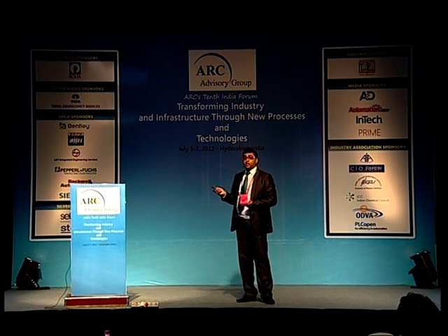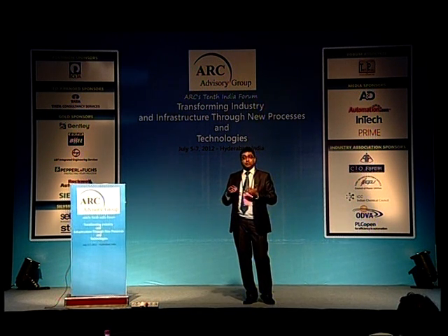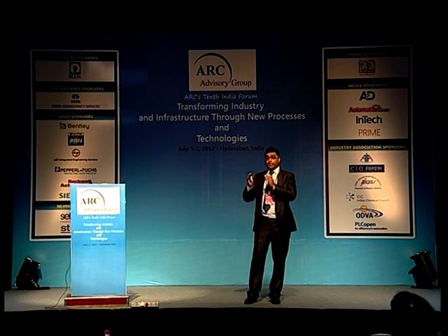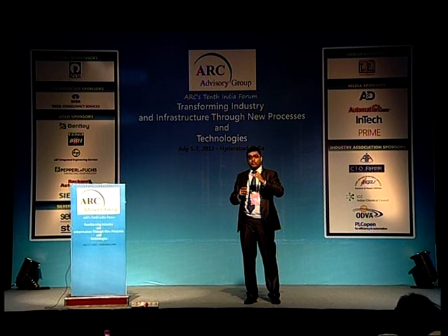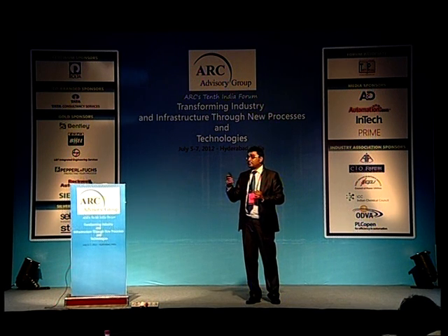The other thing which is provided is the hotspot. It is not really a hotspot, but what we are presenting here is the maximum metal temperature calculated by the system. It tells you every time which is the tube, which is the assembly, which is the location of the point where the maximum temperature is happening. And you can make a trend, because the system is very user friendly for making a lot of trends. Then you can easily see where your maximum temperature is happening.